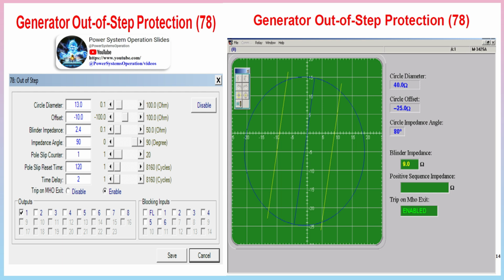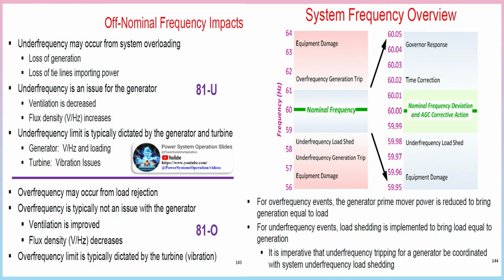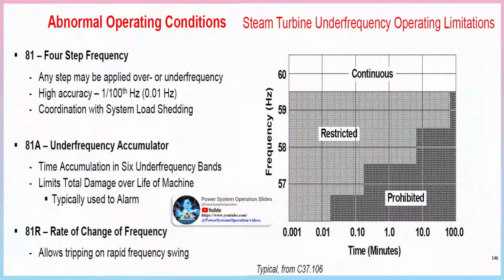more common with modern EHV systems where system impedance has decreased compared to generator and GSU impedance. When a generator goes out of step synchronism with the power system, high levels of transient shaft torque are developed. If the pole slip frequency approaches natural shaft resonant frequency, torque produced can break the shaft. High stator core and iron flux can overheat and short the generator stator core, and the GSU is subjected to high transient currents and mechanical stresses. Low vacuum protection.